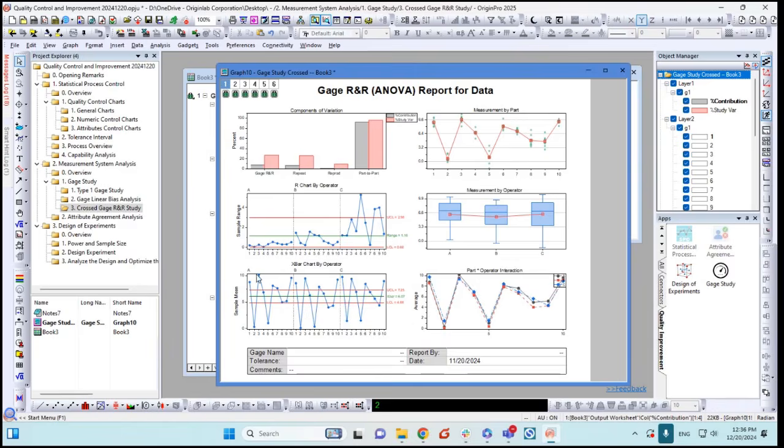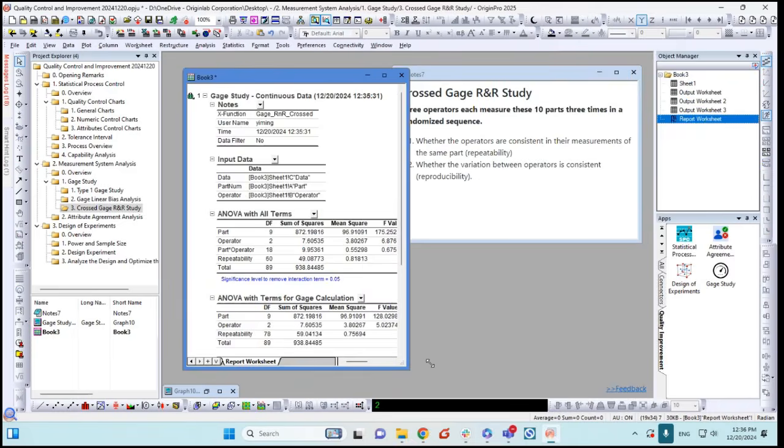And for the sample mean for the three operators, they are way beyond the confidence level, which means the variation is not from the operators, it is mainly from the different parts. Okay, and we can also check the measurements of each part. What's more important is this result table.